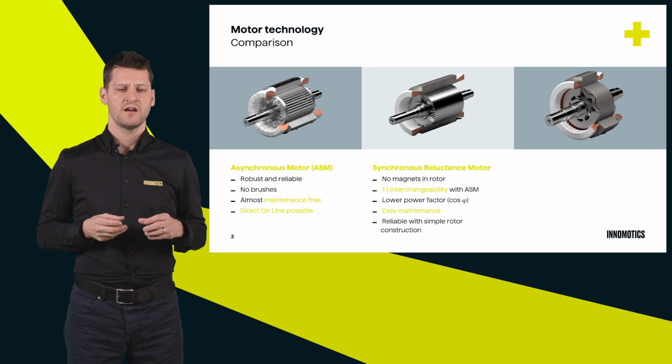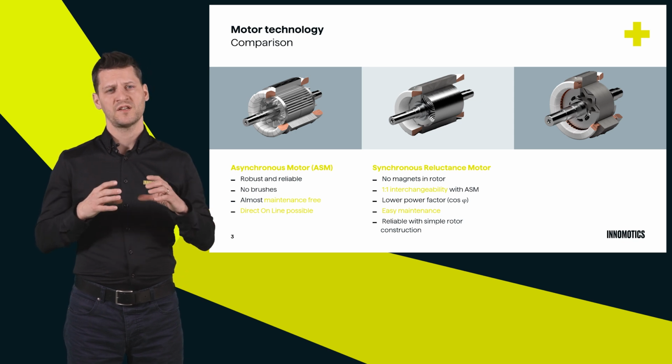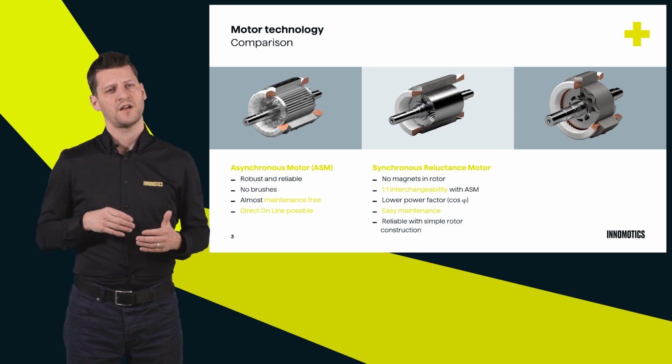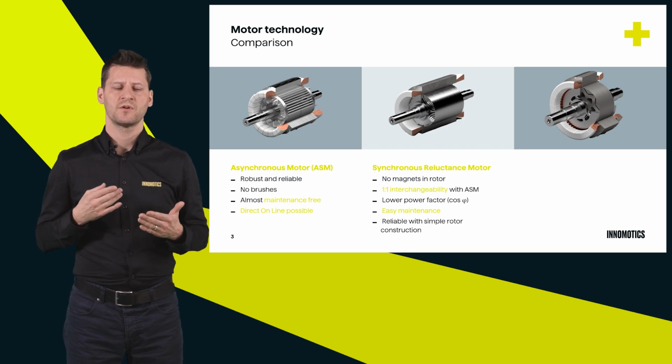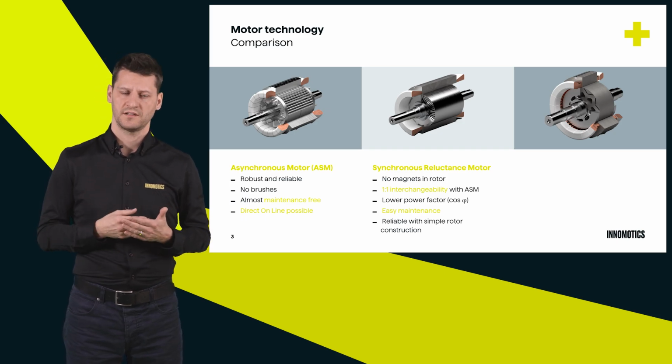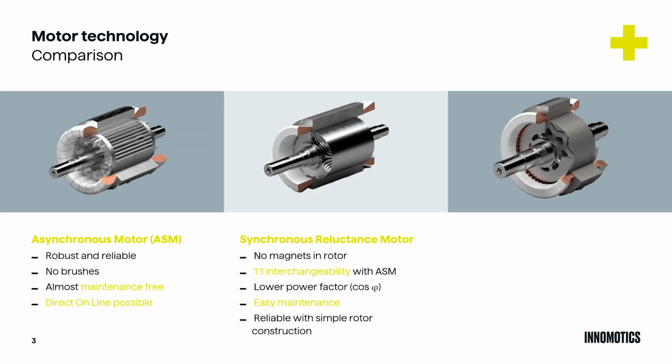As you can see, on the rotor plate, there's always 4-pole design. There are no magnets inside, there is no squirrel cage, therefore there is no induced current in the rotor. That means this motor is the coldest one among all those three technologies.